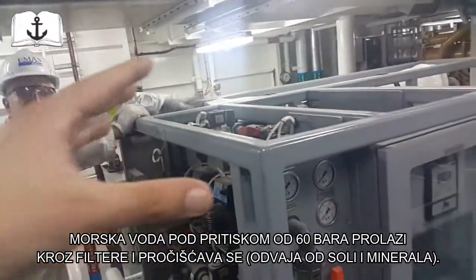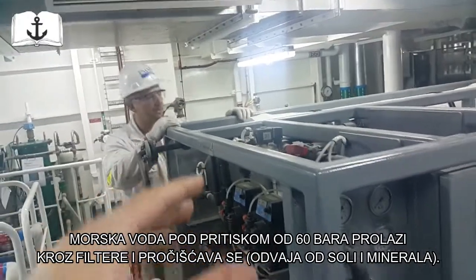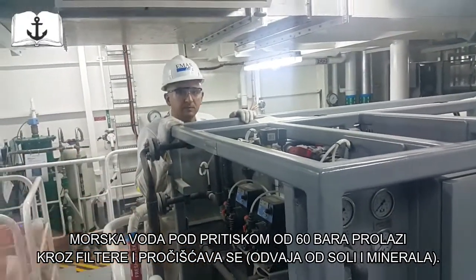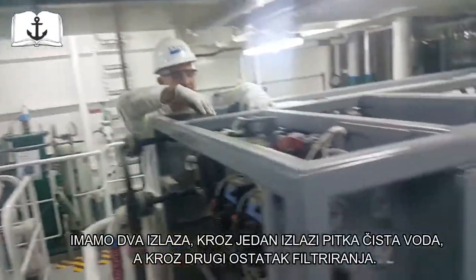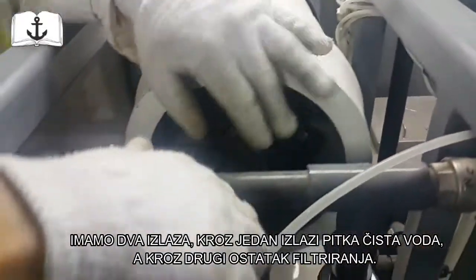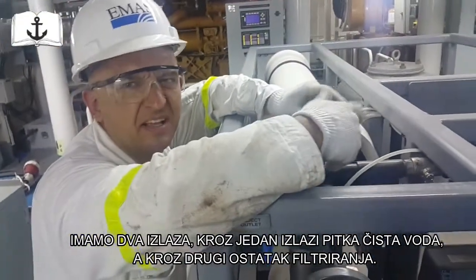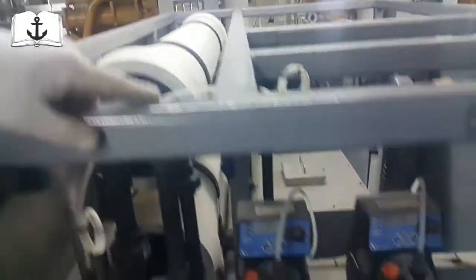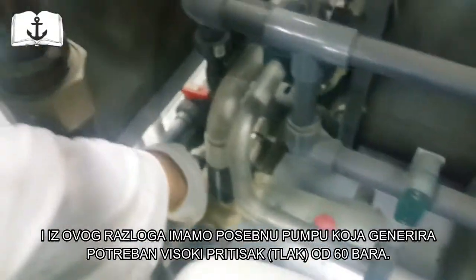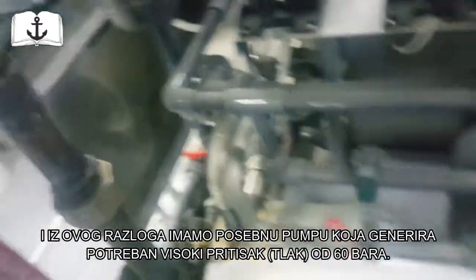So you're pressurizing that water to 60 bar and pushing it through the membrane. The salt and the dirt are left inside, and you have two outlets here: you're making fresh water, and you're making brine, which is like residues. For this purpose, you have the special high pressure pump here. We call it the cat pump. It's a 3-piston pump, very strong, and it makes 60 bar. There's an electric motor for it. So yes, it's quite simple.